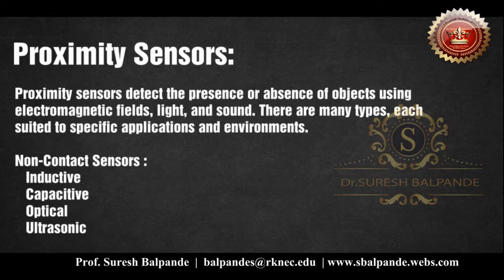So that is nothing but the contact based operation, whereas non-contact based operations include inductive proximity sensor, capacitive proximity sensor, optical proximity sensor, and ultrasonic proximity sensors. Inductive, capacitive, optical: the name itself indicates the principles involved in those proximity sensors, namely variation in inductance, variation in capacitance, and variation in optical properties.